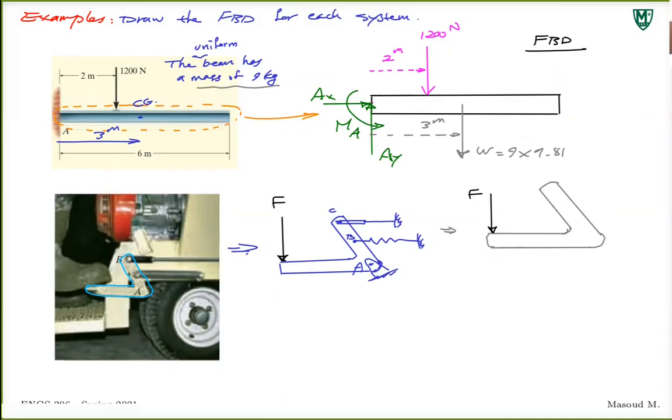There is one obvious. Cable force. We have cable force at which point? C. C, exactly. We have cable force. And it's in this direction. It's under tension. So T, C, applied at point C. What else? Another obvious one. There is spring support on point B. Exactly, Nathaniel. Thank you. That's also spring support at point B.